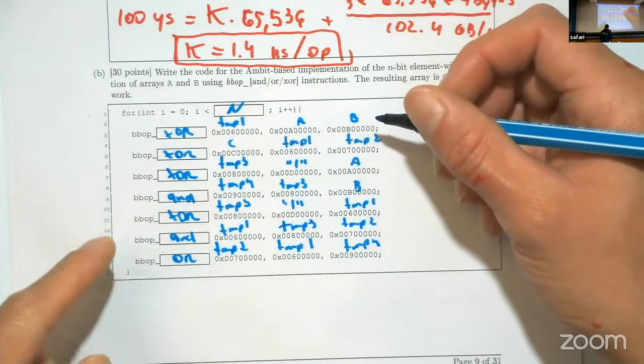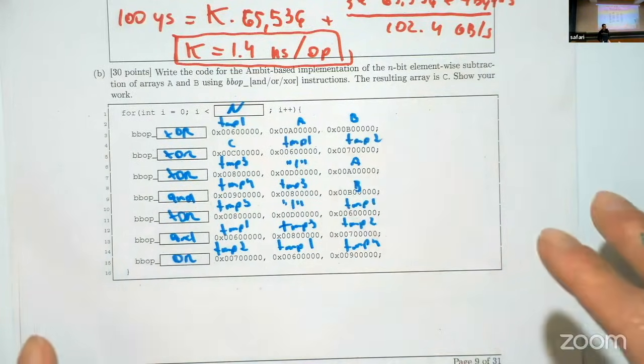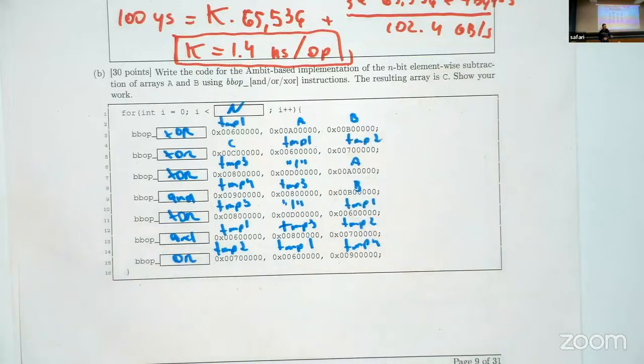It's because this is repeating n times. The way that this is implemented in hardware later on is that there is an internal counter that is counting for this I and figuring out the offsets. The question does not ask you to figure that out, but if you go back to the SimDRAM paper that I presented some time ago, I explained there is a control unit that translates these bbop instructions into proper activations, and over there the I is a parameter, but it is transparent to the user, so you don't need to worry about it.